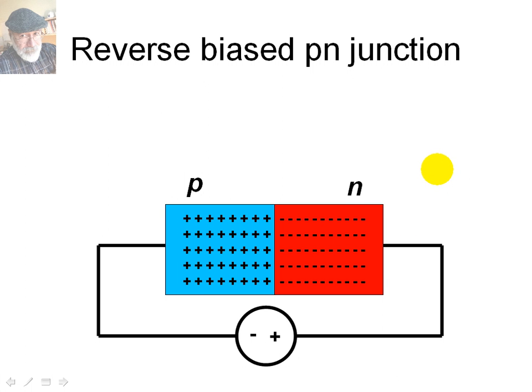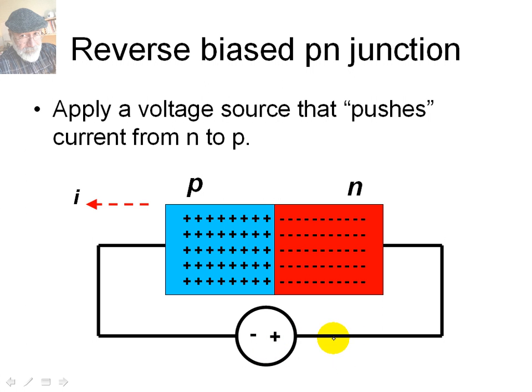Now let's apply a backwards bias to the p-n junction. We are trying to take current out of the P material. That is, we're trying to feed electrons on the left of the P material. If we do that, those electrons will recombine with some holes on the left of the P material, and the density of holes will decrease on this side, on the left-hand side of that.